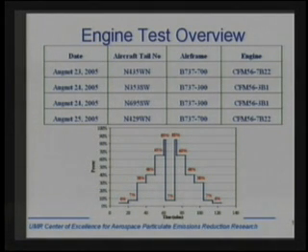We would start at idle, warm the engine up, and then gather data at an idle power point, and then at a ground idle setting, okay? And then increase at pre-selected power settings, okay, up to the maximum that they use at Oakland. They don't need 100% power to take off at Oakland. They typically take off with a derated thrust at 85%. We drop down to the baseline idle condition and then back up to 85 to get repeating data. And we did that process for each of the aircraft in question, okay, measuring both engines on the aircraft at the same time.